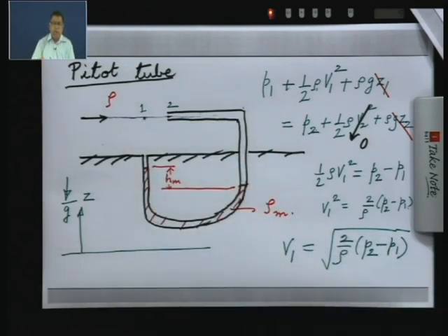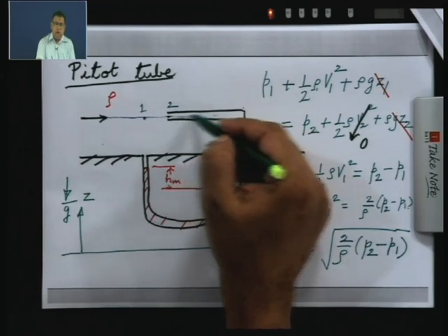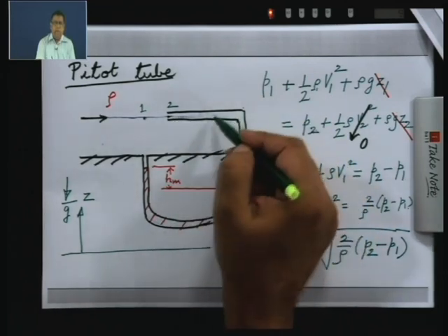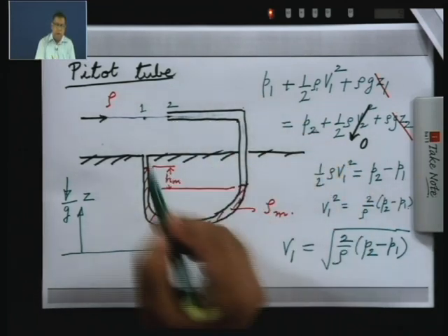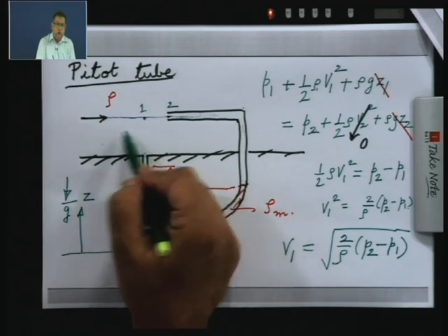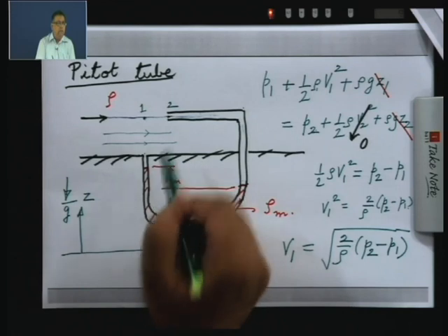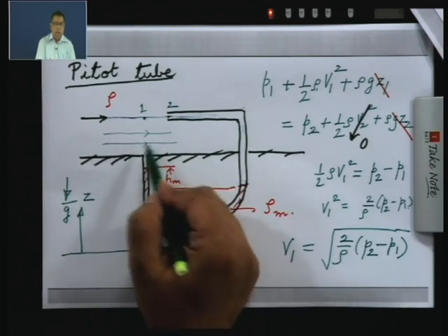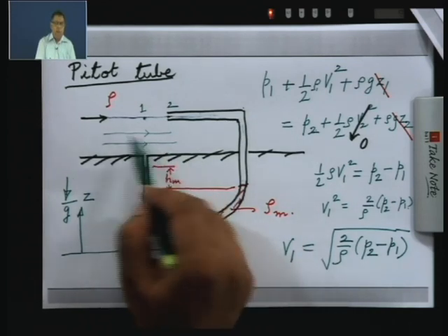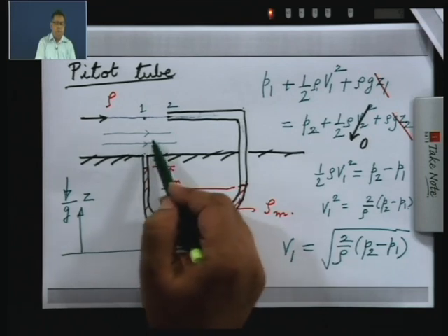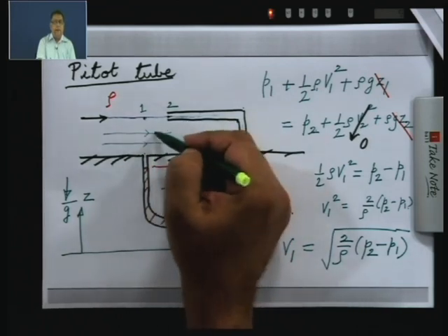Now, let us see how to find the difference in the pressures. Now, this column of fluid is at rest. So, we can apply the equations of hydrostatics here, but the fluid above the wall is not at rest, it is flowing over the wall, but in this particular flow the streamlines are parallel to the wall because it is inviscid flow, and they are straight lines.